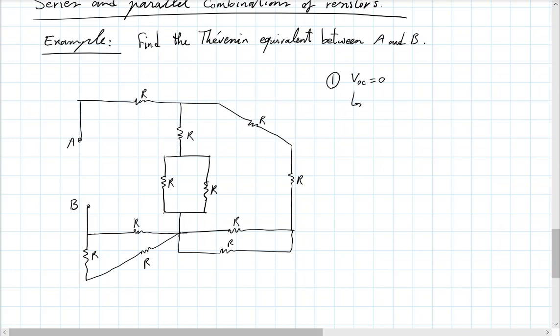So you can calculate this using the method of solving circuits, which is KVL, KCL, element relationships. And similarly, you can calculate your short circuit current, which is, well, maybe let's emphasize that that would be when you put a line there.